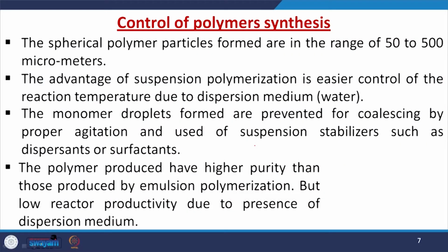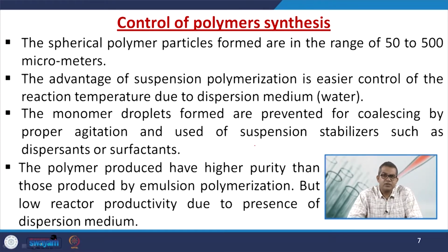So, we are always looking for larger surface area, but sometimes if we use these things excessively, the polymer particles may become brittle, and sometimes the regeneration or recyclability of these particular polymer particles is not at all feasible. So, they offer a very wide spectrum, a very good approach for various kinds of practical applications. When we talk about the advantages of suspension polymerization, this particular polymerization process is easier